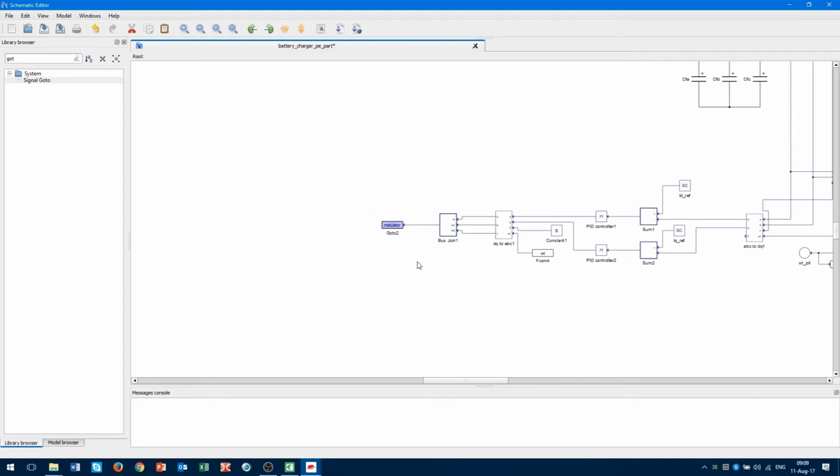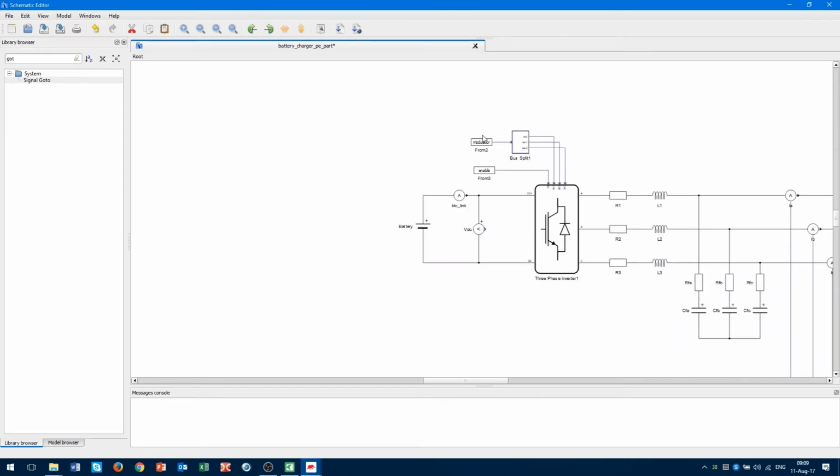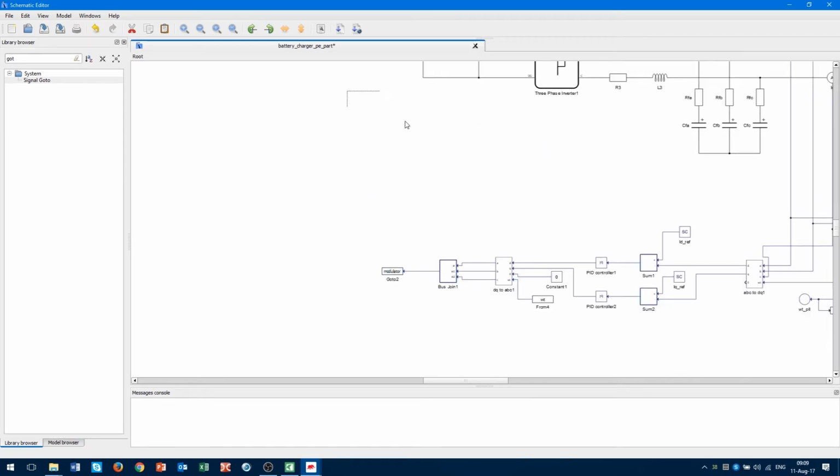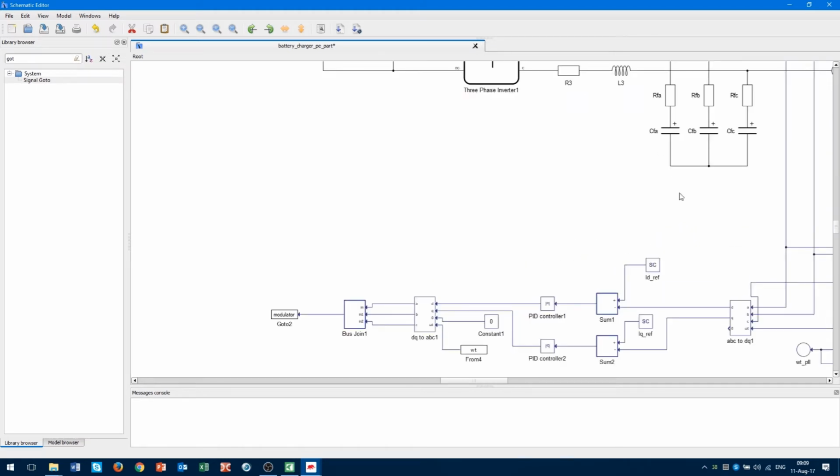Now we have made the basic control, and here on this clean area we will make overcharge protection for our battery. We want to enable charging when the battery is not fully charged and to disable charging when the battery is charged. So let's start with a few elements. The first one will be comparator. We will need two comparators.